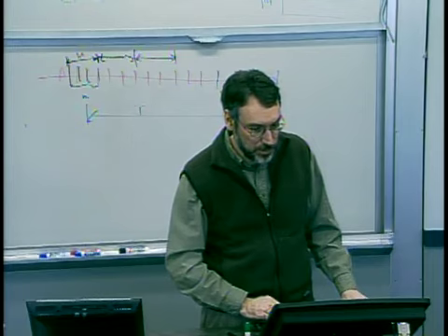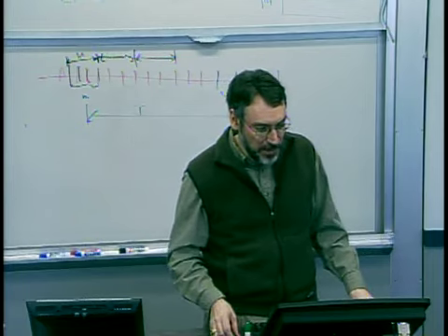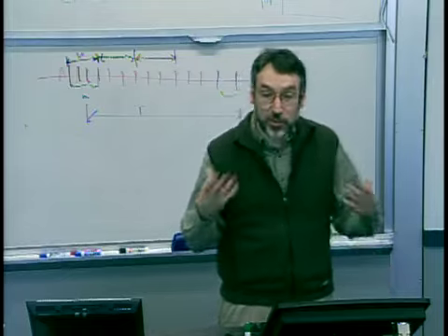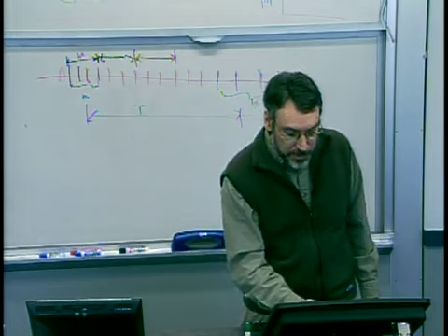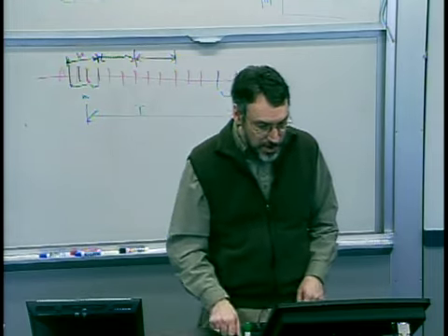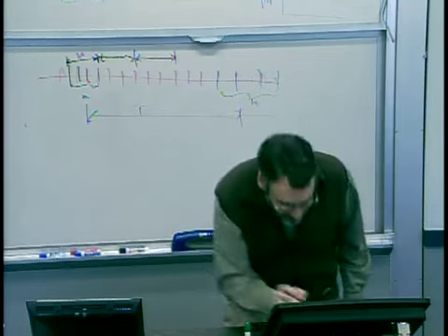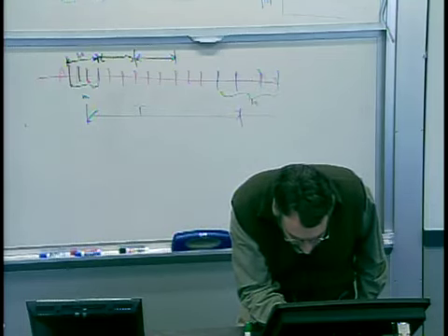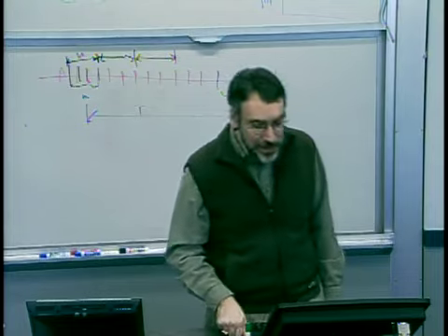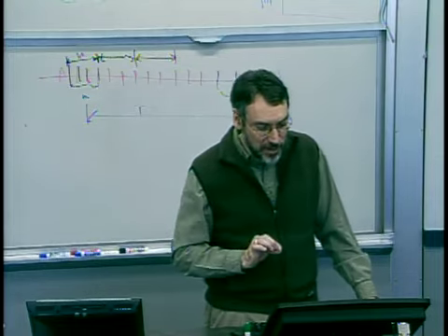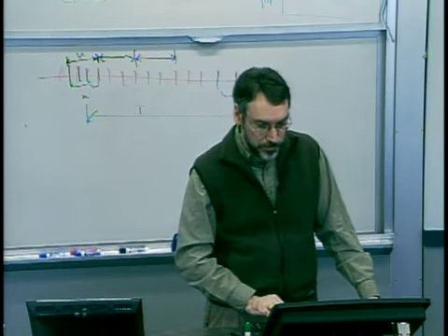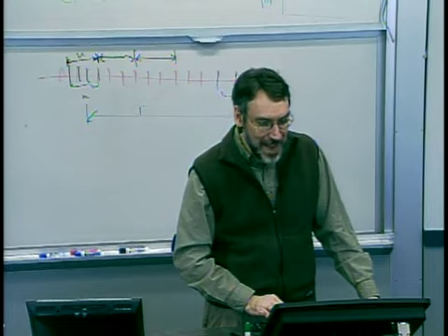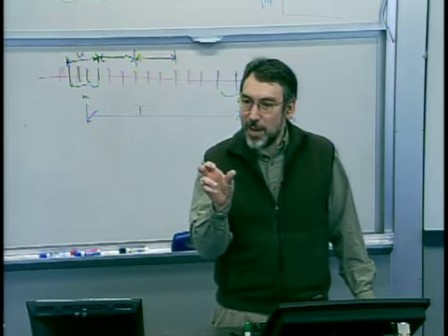So, whoops, what happened here? So here's the picture where my CPK and CP are both 2, perfectly mean-centered. Again, that's the 6 sigma distance here between the tail. And we said the probability of having way out here in the tail, that's my PE, my fraction of non-conforming, and it's about 1 part per billion, maybe 2 parts per billion. But now let's say that I actually have a mean shift, where I've actually shifted by 2 sigma.